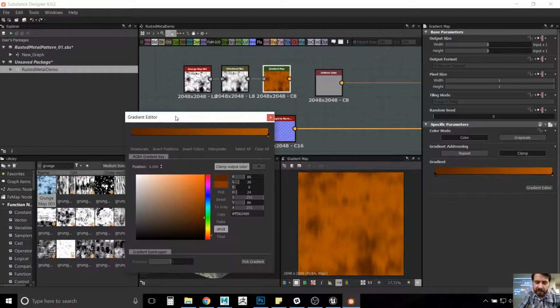I'll just leave this up for right now and come help you guys out. If you've accidentally created a third point in your gradient, just hit clear all and click on the end of it. If you accidentally created multiple points in your gradient map, just hit the clear all icon up here, and it restores the grayscale image. So you want to go for a darker brownish color to a brighter orange. That should give you what you need. And you can use different grunge maps, play around with more points.